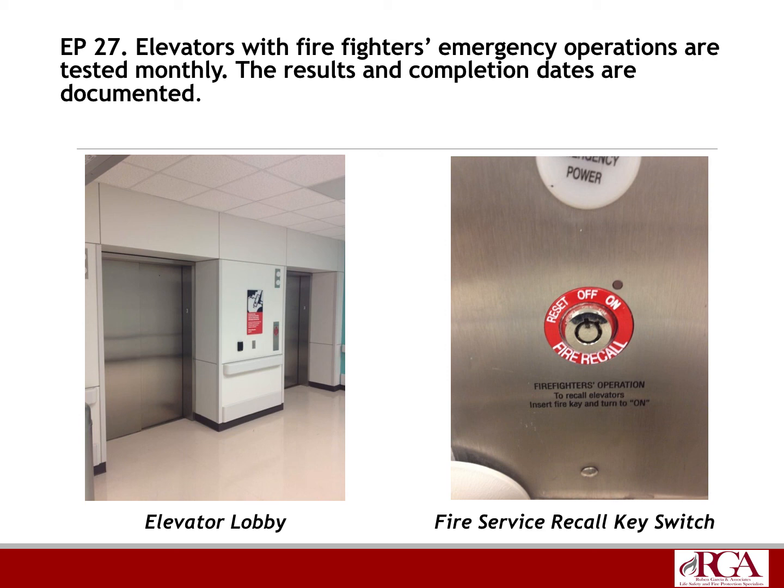And either your elevator vendor's doing this on a monthly basis, or your in-house maintenance staff are doing this. The purpose of this test is to verify that your phase 1 and phase 2 firefighter operations are working properly. This is important if you have a high-rise building, or any building in particular, it doesn't have to be high-rise, it could be a low-rise or standard 3 or 4 story building. This is going to allow firefighters to use those elevators to further either fight the fire and or rescue patients, staff, or visitors. And so this needs to be checked monthly.